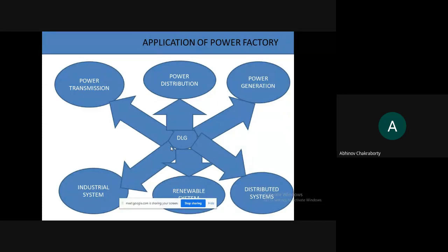So for that, I have to have a separate system that I design, and that is said to be the industry-based system, whereby you have separate lines for your power control unit, separate lines for your motor control unit, separate lines for your automatic power factor control and rectification units, whereby even the capacitor ratings, the series capacitors that you have connected for power factor boosting, are also mentioned in this particular system diagram. So that is why your industrial systems become that important.